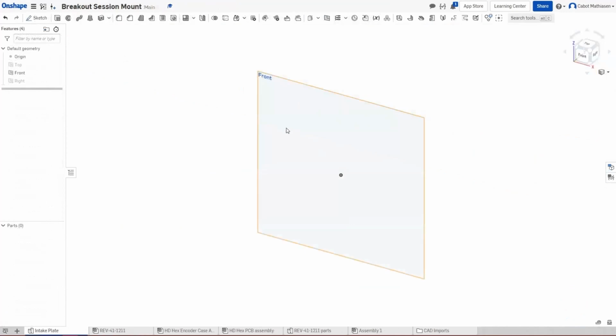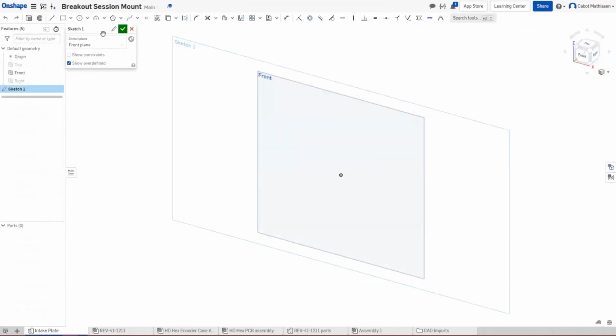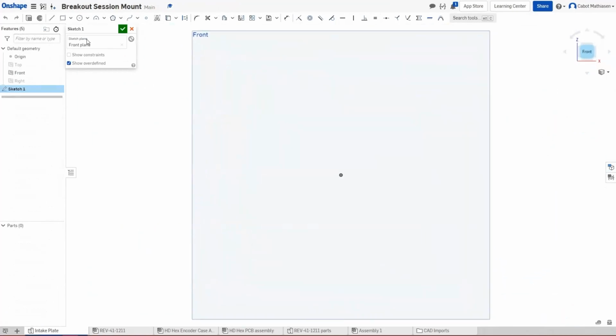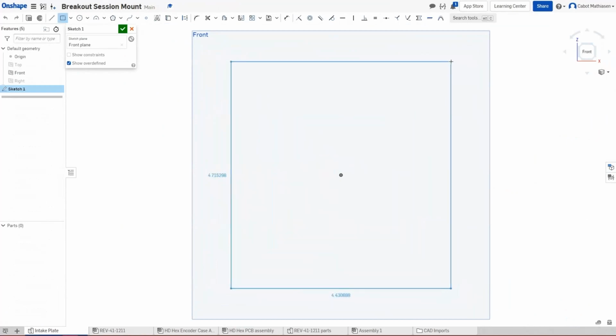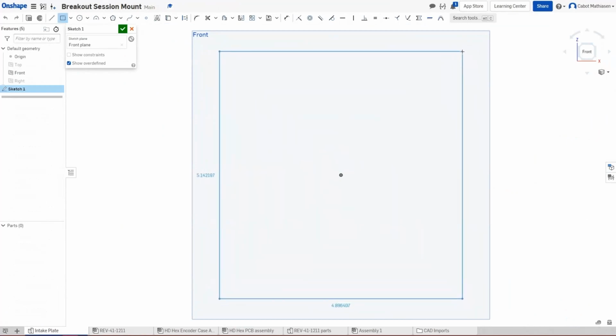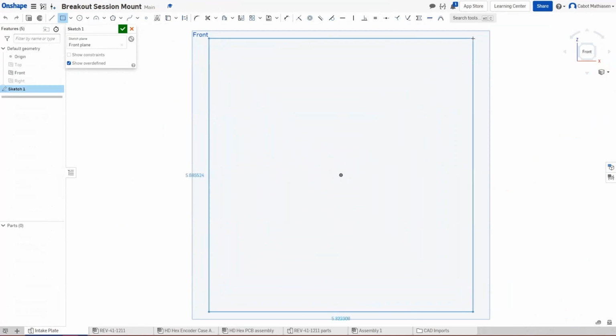Here I'm going to click on a plane and press the sketch button up there, or you can do Shift S, and then I just clicked on the front to rearrange it, and there in the left hand corner I clicked on rectangle. There are two types, center and corner. It depends how you make them. There I did circle, so that's button C.